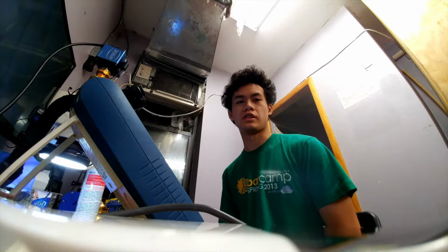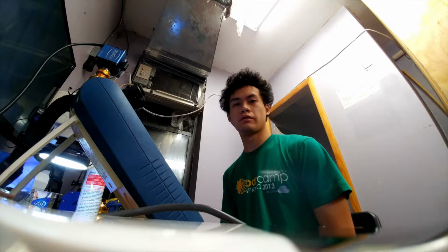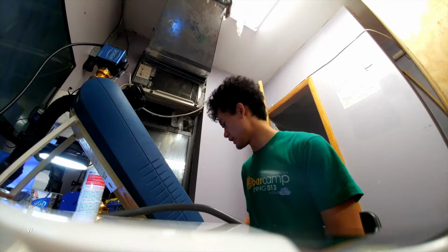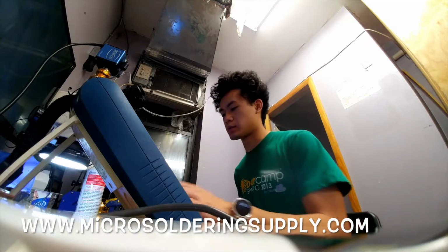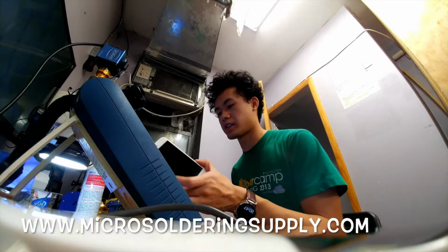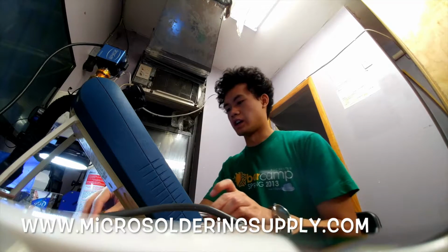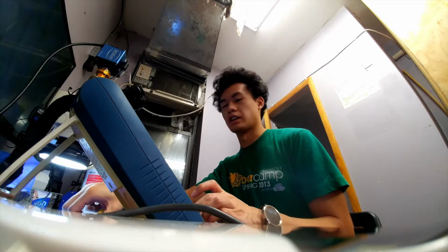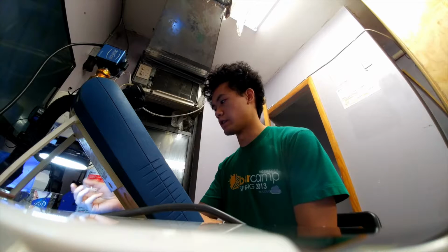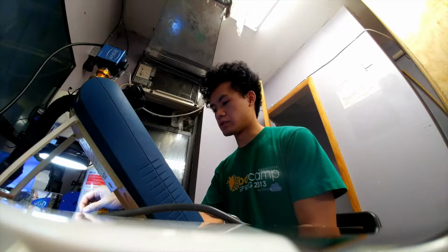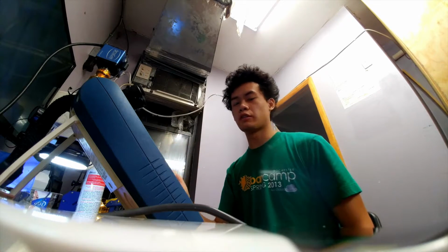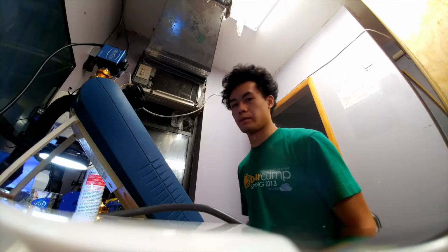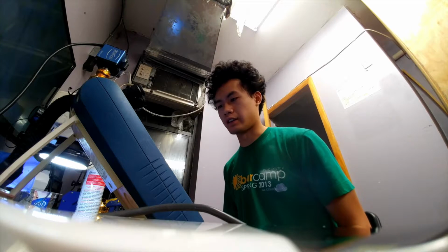This is Jason from MicroSolderingSupply.com, and today I'm going to be going over a very common issue you see, which is iPhone 6 sudden no backlight. A lot of times what happens, like this one did here, is the customer comes in and says all of a sudden they woke up one day and they couldn't see anything on their phone screen, or all of a sudden it got hot and their phone died. When you turn it on, you can see a faint Apple logo, but it's very dark, you can barely see the picture, and so that's called no backlight.